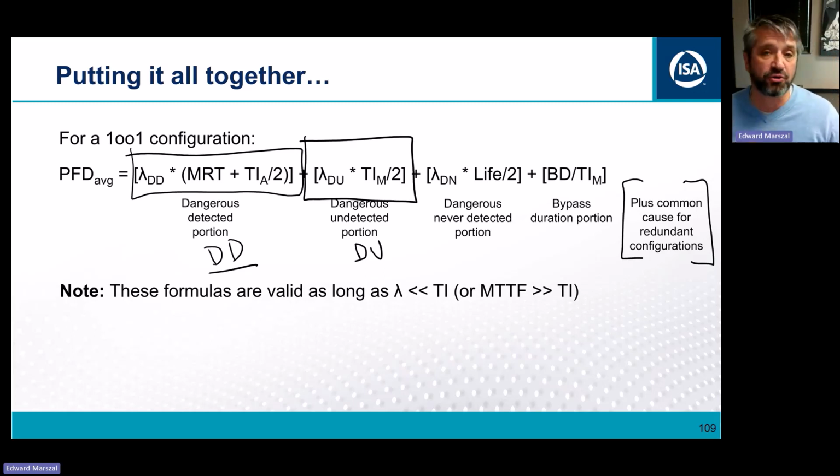But you can also make the choice when you detect a failure. So let's say I have an SIS level measurement and a BPCS level measurement, and I have a diagnostic that's a deviation alarm between those two level measurements. If that deviation alarm goes up and says, hey, one of these two transmitters is in the failed state, and it very well could be the level transmitter in the SIS that's in the failed state, are you going to shut down? Most plants are not going to shut down on that deviation alarm.